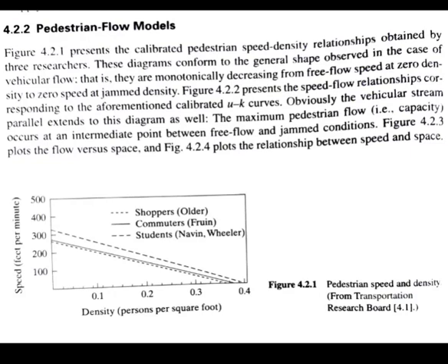So what is the density and what is the delay for the intersections, and based on all these we'll be formulating certain mathematical models, and based on the equations we'll be arriving at a certain range of values for a certain section. Okay, so the range varies from A to F, and this is as per the HCM. HCM means Highway Capacity Manual. So all these values are based on the Highway Capacity Manual.